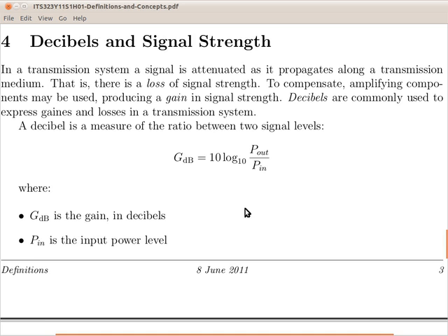Another example. So that was an audio system as an example, which amplified the signal. Our communication system, I transmit with some power level, 1 milliwatt. I've got a wireless device, a Bluetooth device, transmitting with 1 milliwatt. The signal gets weaker over distance. It's received with 1 microwatt. So here's a communication system. We start transmitting at 1 milliwatt, the receiver receives 1 microwatt.